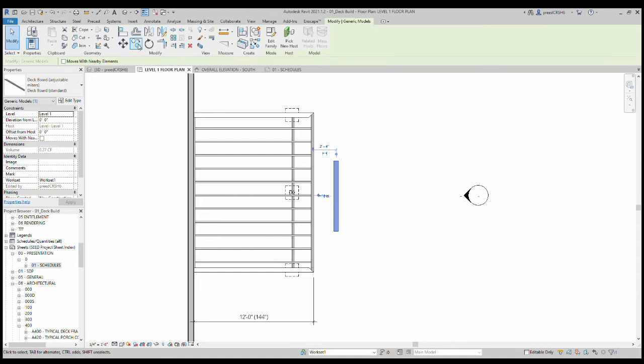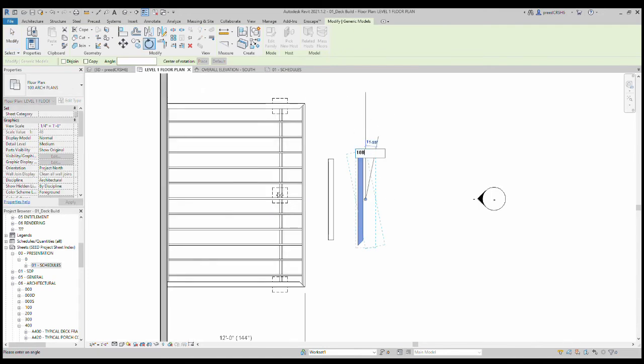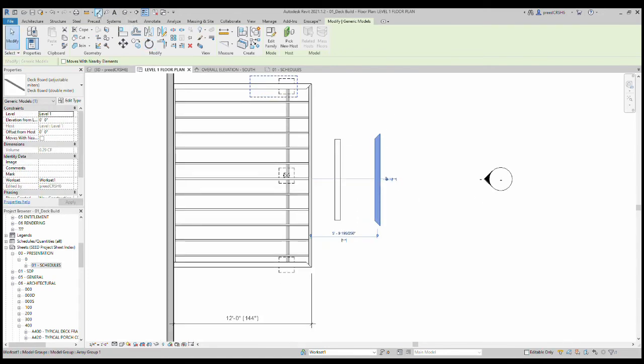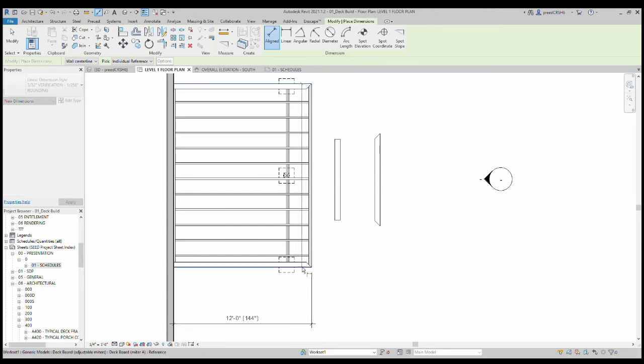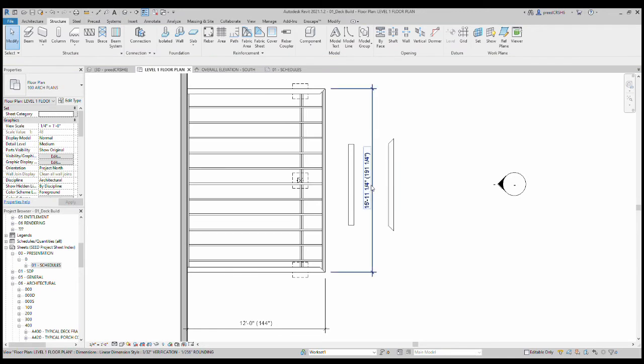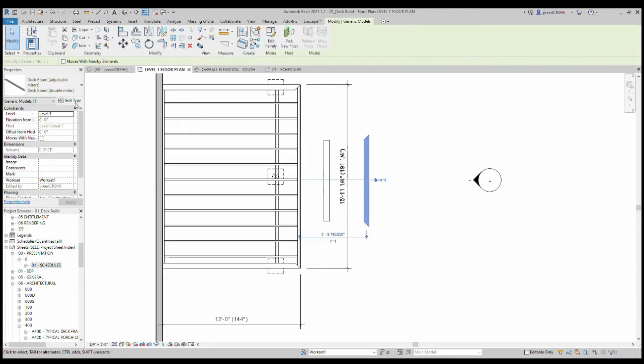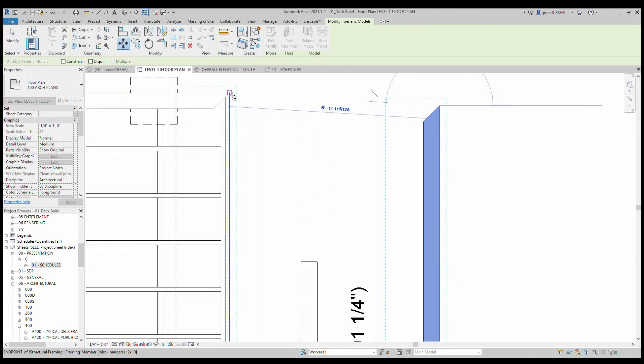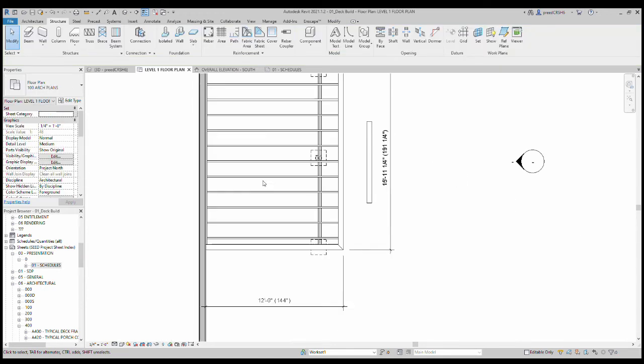And then I'm going to have another one that's the double miter, like so. Now double check, we didn't really run a string here. That's 15 and 11 and a quarter, so that's a really odd size, but it fits within our 16-foot deck boards. So we can make that work. So now you've got a picture frame.